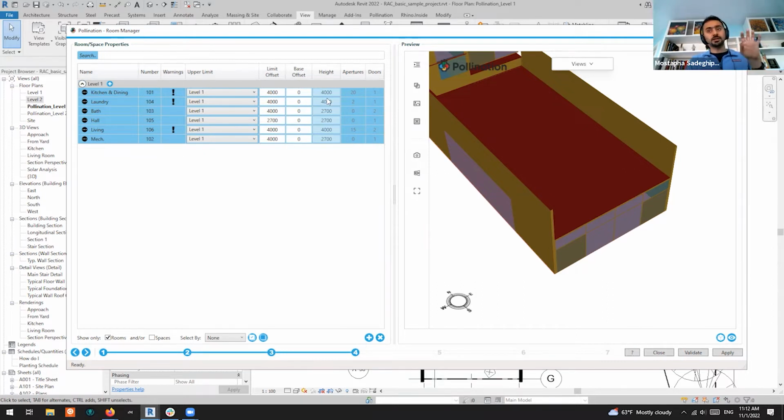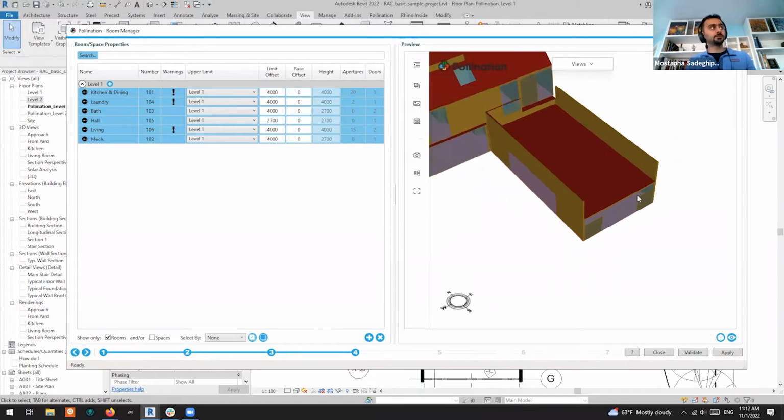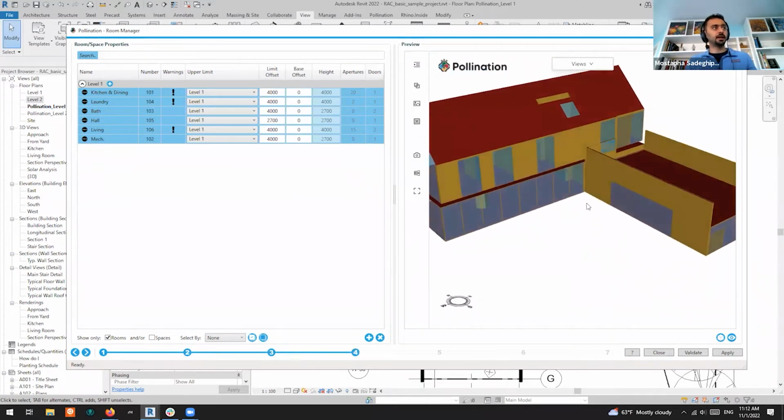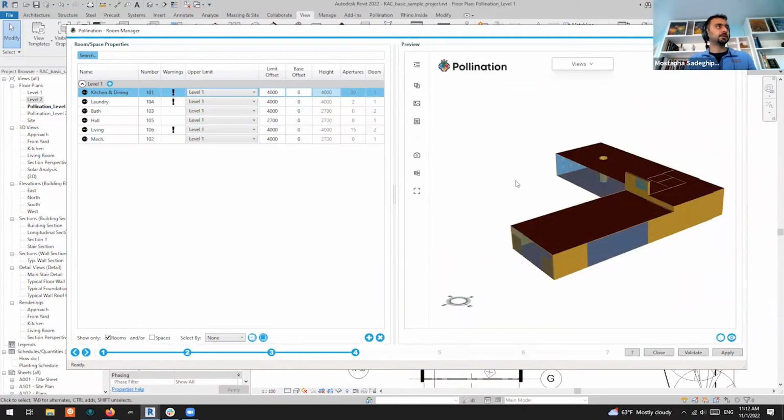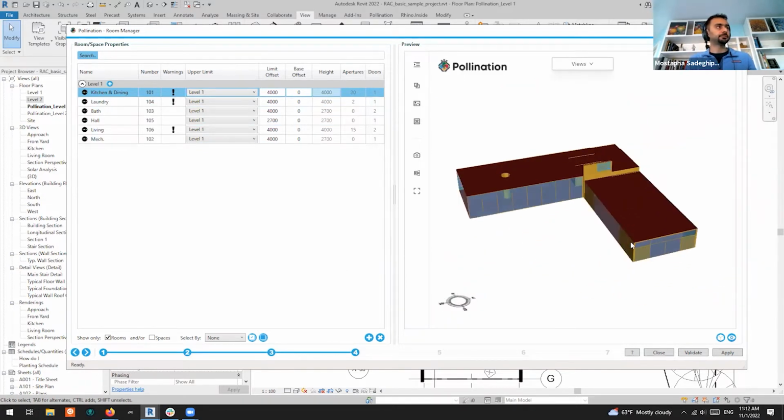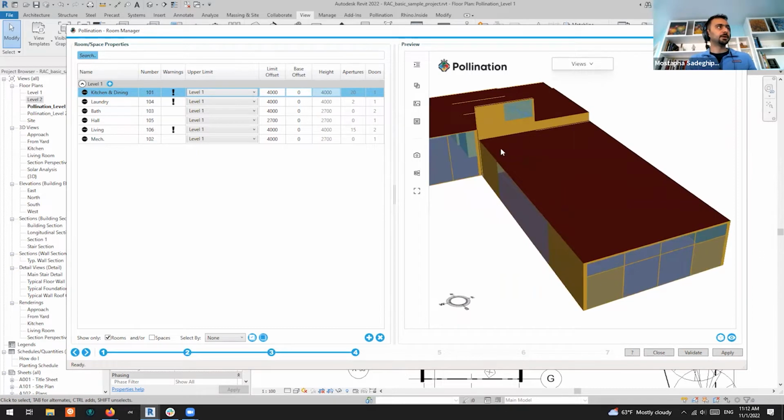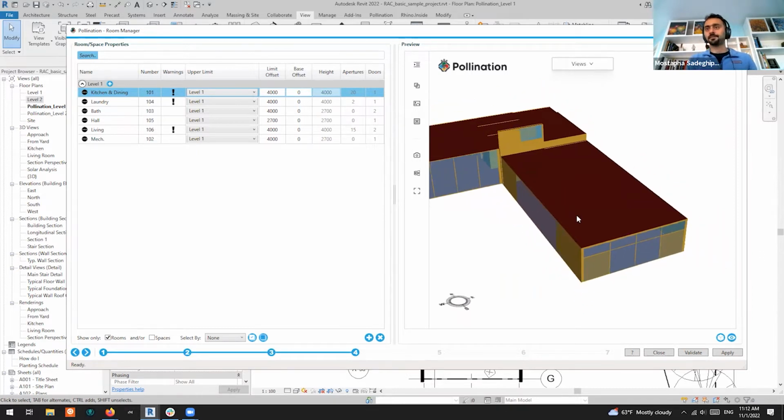If you make any changes in your Revit model that you want to be seen here, you have to use reload geometry. You see there are 2 of them here. This is reload preview, and then you do reload geometry. So if I do reload geometry, you see it triggers the change to go and reload everything from Revit and see if we fixed anything. Hey, here we go. So this one is already fixed.